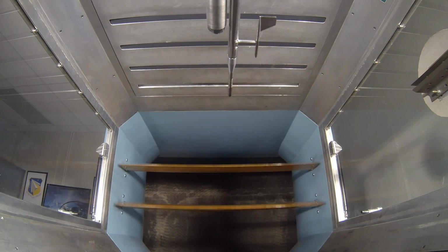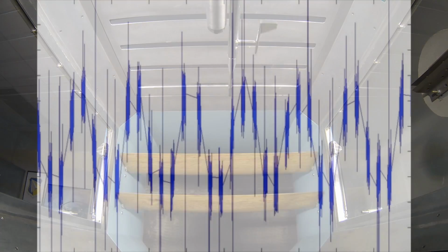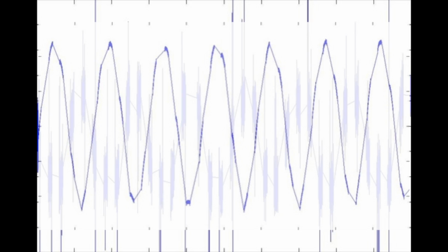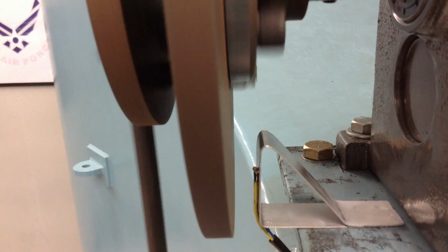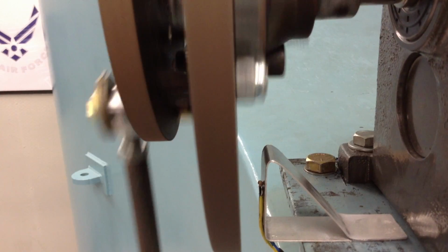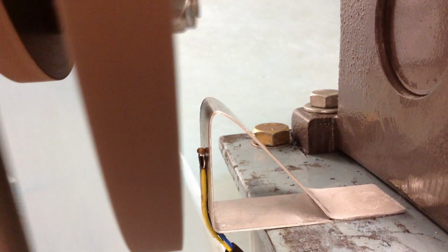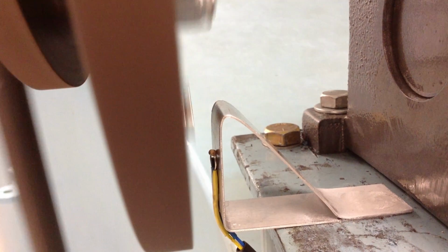The alpha probe, however, was about the best data we had recorded. The frequency of the alpha probe was matched to the encoder frequency. This obviously is a good sign. The Hall effect sensor, however, was not very accurate. Due to the low sensitivity of the Hall effect sensor, the results were not conclusive. The RPM, which was calculated, was not the same as what was recorded from the Hall effect sensor.